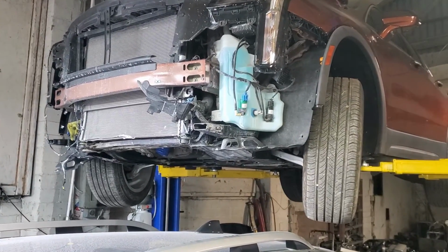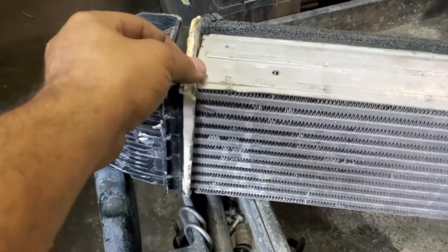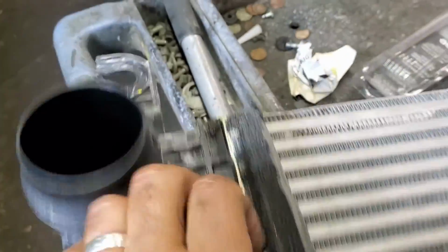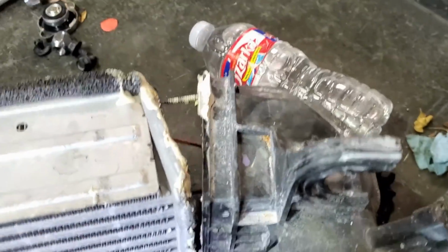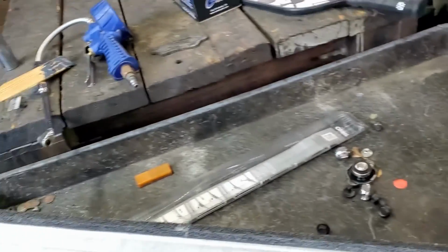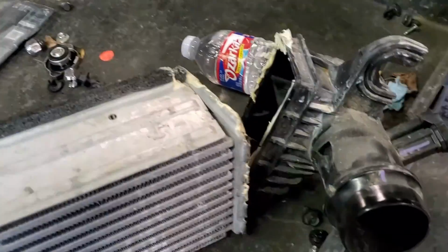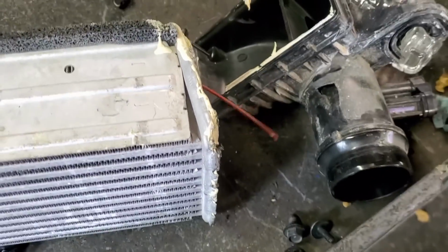Okay, I need to look at it. So they got the Caddy on the lift and they took the front bumper off and guess what they found? Look at the intercooler. Somebody had done this before and he said this piece was like that, right? Yep. Okay, and it has a crack here. So this is definitely where it was leaking. That's from the other side, right? Yeah, this goes on that side, your side, on the passenger side. Okay, so this is definitely the problem. Should be fixed. Yeah, definitely, yes. That's a bonus footage for you guys.